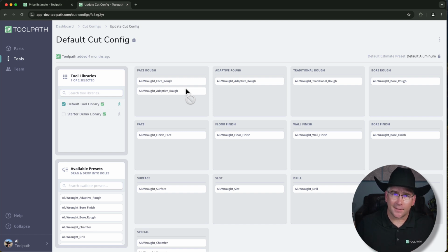If a pocket has a 1/4 inch radius, we know that we need a 1/2 inch tool to finish that pocket. But if it's a very large pocket, we may later inject in a larger tool to rough it out for speed reasons. But suffice it to say that the first thing the system does is say, what's the tool geometry that needs to fit?